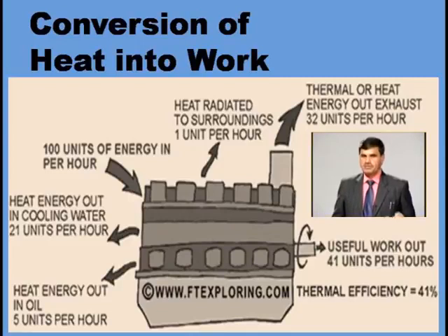Between the cylinder and piston, because the piston is moving inside the cylinder and both are metallic, there will be a lot of friction also. So some of the heat energy which is applied is wasted in overcoming that friction. For reducing friction, lubricating oil has to be between the wall of the piston and the wall of the cylinder.